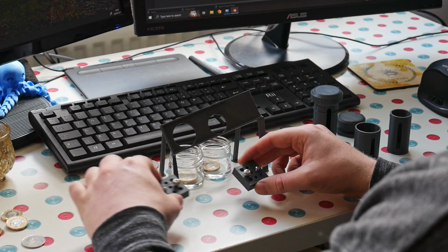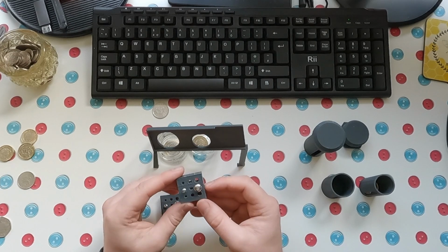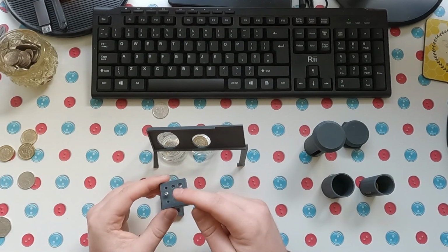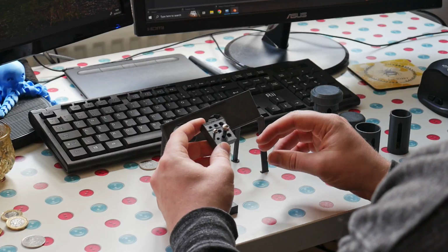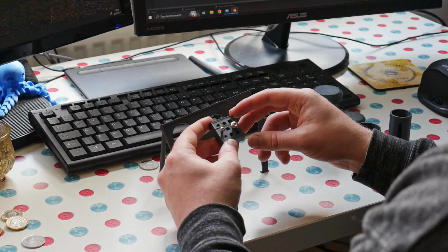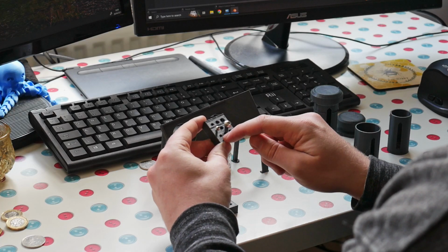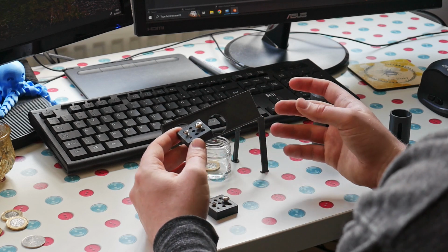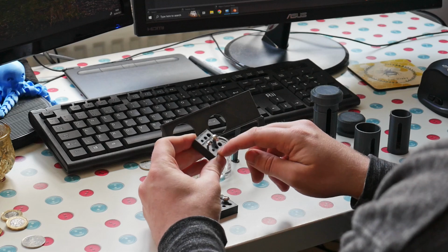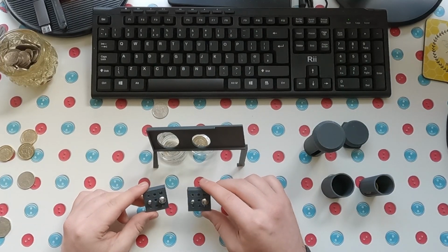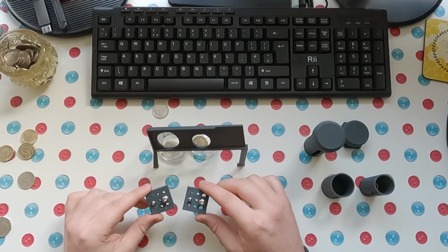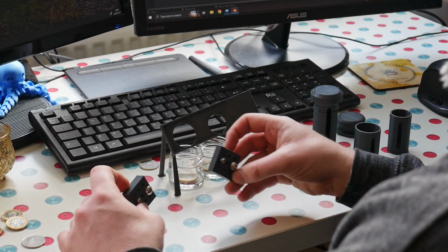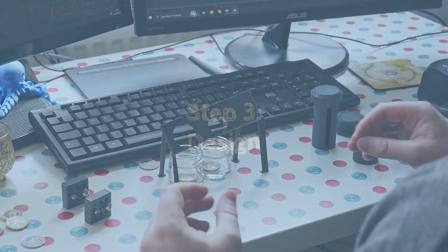And then with these 2, if you have a look at these top 2, these were printed with the threads, and you could probably screw these in to make them work, but they were very tight, so I just cleaned them up with a tap set, and then these are just to test the actual diameter of the overall bolt. And pretty much this just tells me that my printer slightly undersizes holes, which is something to be aware of when making the final design.